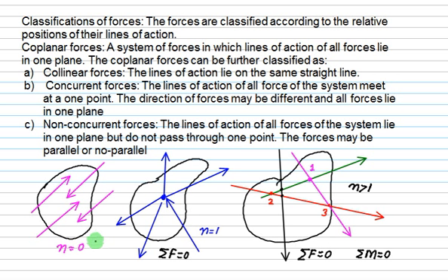For this one, the force is acting in only one direction. If I say this direction is Fx, only one condition is required, that is sigma Fx equals 0. If I say this is the direction x, you need not balance along y, you need not balance along z also. But this time you have to balance along x, y, z. So only one condition, 3 conditions, and we require 6 conditions. So this is how we can develop the equations in mechanics, and once we develop the equations for concurrent, non-concurrent or collinear, we can successfully solve any problem.